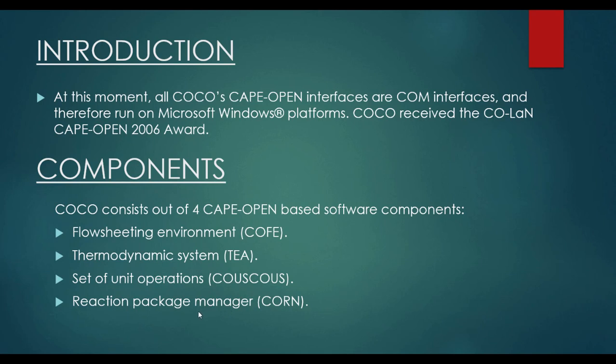And for example, you have reactions, like you want to perform a combustion or some chemical reactions, then you can use this reaction package manager. Like for example, when benzene reacts with hydrogen, it forms cyclohexane. So you can put that reaction into the reaction manager and import that reaction into the main flow sheet inside the reactor.